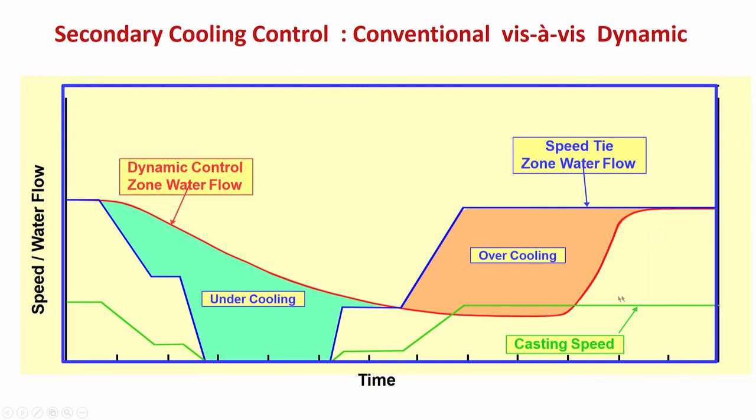You have decreased the speed, so the water is also coming down, but the cooling possibly is maybe more, and then when the cooling has come down, there is a possibility of reheating, that is, whatever molten steel was there is trying to heat up, but at that particular point of time there is undercooling, because you do not have sufficient water to cool that.